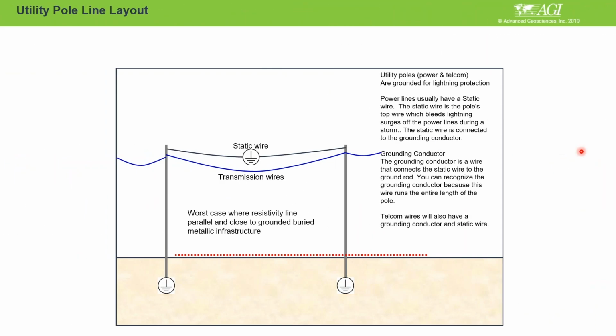The other thing is typically for grounding grids you're checking, especially for electrical utility companies. They have grounding grids at the high voltage power towers, and also, for example, in recent days you may see lots of wind power around the electrical production, and those wind towers also have grounding. So you need to check that grounding.